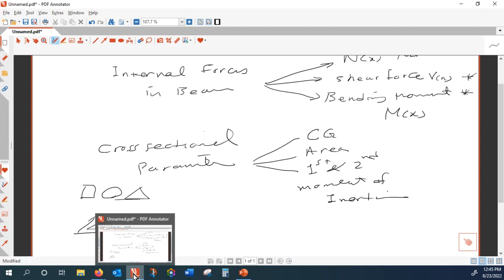All right. Anyone remembers when it comes to finding internal forces? We mentioned there are two techniques. Do you remember those techniques? How do we find them? The first technique goes back to last week. It was through the free body diagram. And the free body diagram is useful when you want to identify the internal force at one single point.